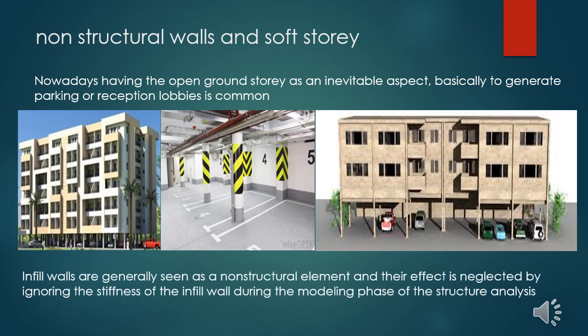Non-structural walls and soft story. Nowadays, having an open ground floor is common. As shown in the figure, clients usually need parking on ground floors, or a reception, or make it a lobby. And in these cases, structural engineers generally neglect or ignore the stiffness of the infill wall during the modeling, which is considered a big mistake.